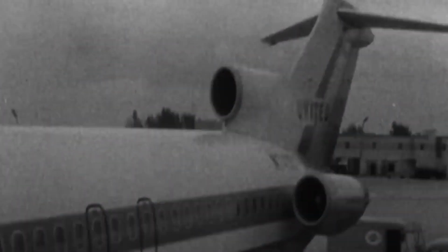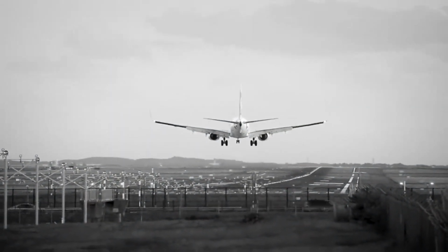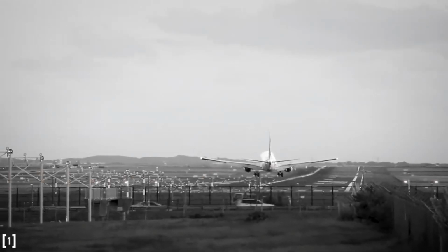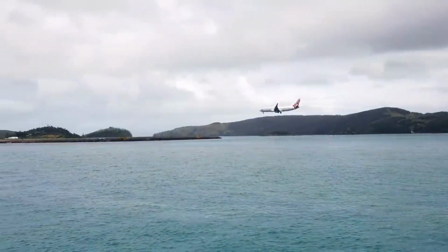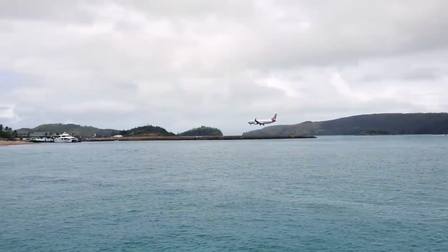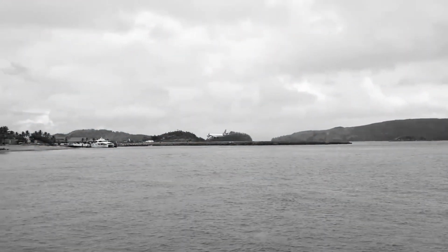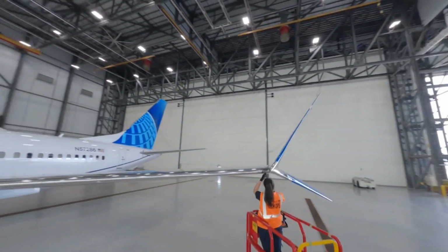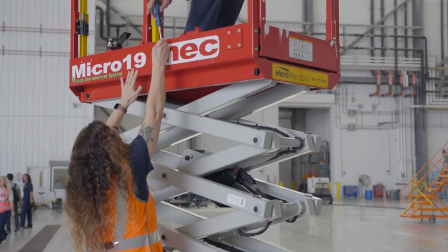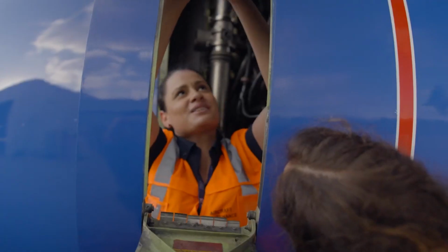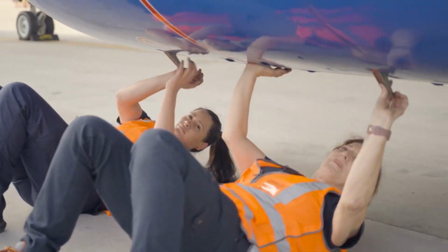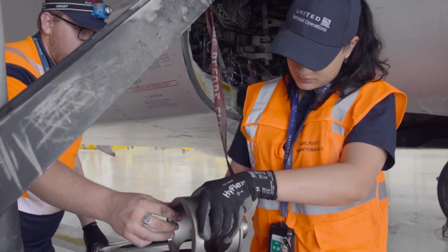Section 43.2 Records of Overhaul and Rebuilding. These terms are not defined in 14 CFR Part 1 and are given full explanation in this subpart. Each term states that it may not be used to describe work done on an aircraft, airframe, aircraft engine, propeller, appliance, or component part unless that item has been 1. Disassembled. 2. Cleaned. 3. Inspected. 4. Repaired, as necessary. 5. Reassembled. 6. Tested. The key difference between the two terms is in determining how the item is tested.